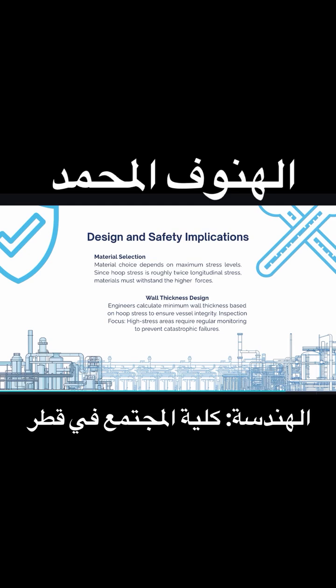Design and safety applications. Material selection. Material choices depend on maximum stress levels. Since hoop stress is roughly twice longitudinal stress, materials must withstand the higher forces. Wall thickness design.